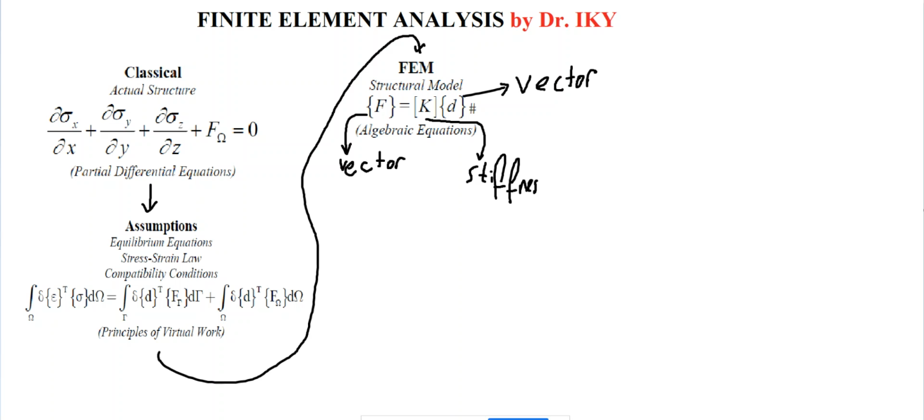So this one is also working with the same ideology. First, we will get the deformations, but if you want more precise results, you will need to use extensometer systems, maybe camera extensometer or digital image correlation systems, for getting more precise deformation results, not just in 1D, but also for the transverse zone or lateral part of the sample.